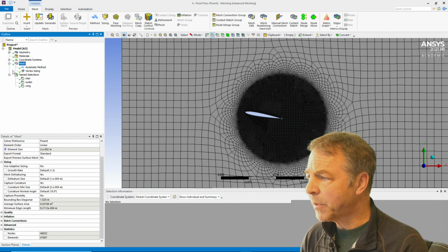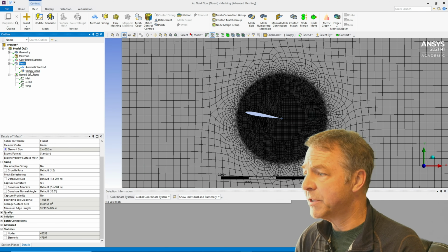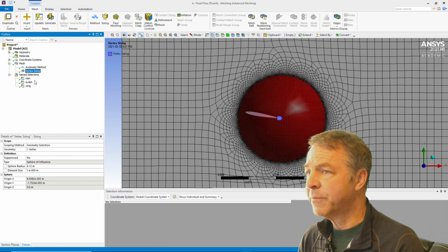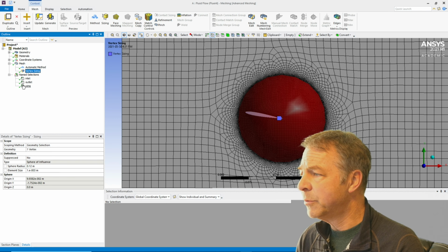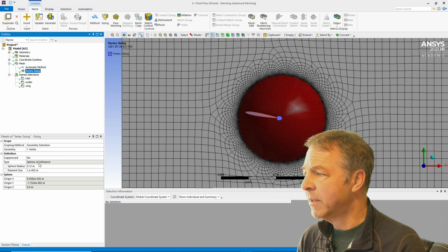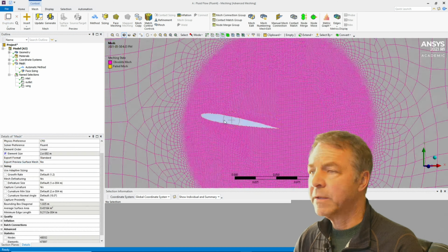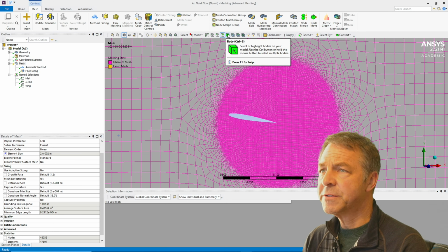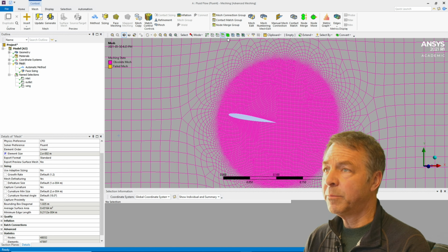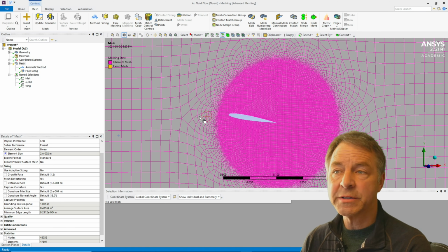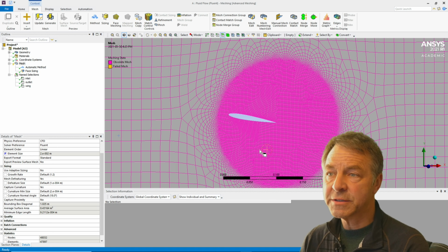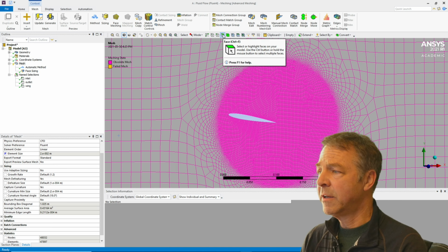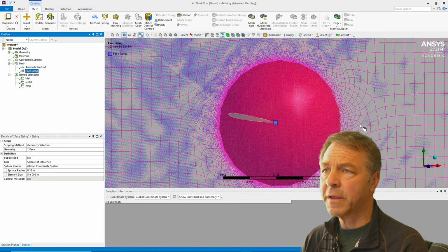So I could try one of a number of different procedures. The first thing I'm going to do is, even though it took a really long time for it to solve that, I'm going to modify my vertex sizing. So that's a good lesson. When you're selecting in 2 dimensions, if you select the body, it will try and calculate grid points for sections of space in this sphere that are not actually on the surface, and it'll take a really long time. If you select as a surface, then it goes quite quickly.